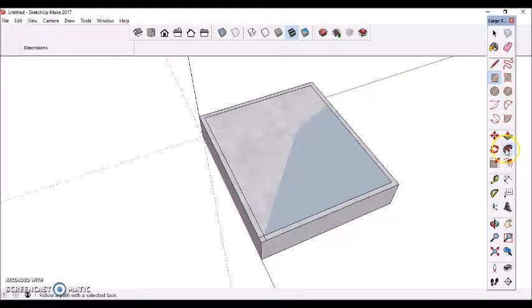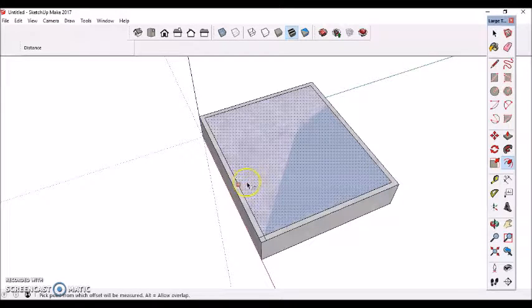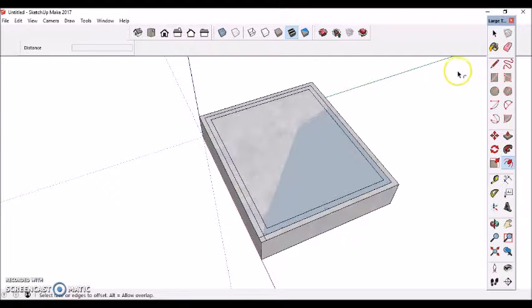And then what we can do is offset tool, click there, and our brick walls 112. Because we've got a rectangle in there, we don't want what's left inside. Just highlight it, press delete. So now there's nothing there.